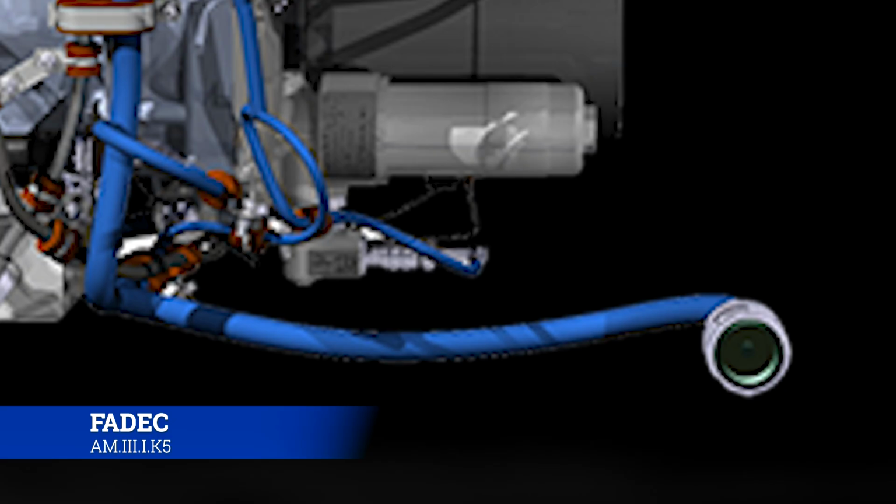On helicopters back in the day, whenever the pilot pulled collective, they had to roll throttle on to keep their engine RPMs where they needed to be, because otherwise you would bog the engine down, you'd lose power, and you'd start to fall by increasing the pitch on the collective. And so you'd see all these pilots sitting around with broom handles going up and down like the collective, teaching themselves to roll their wrist one way or the other to try to get in the habit of doing that. Well, now with FADEC, you don't have to do that.